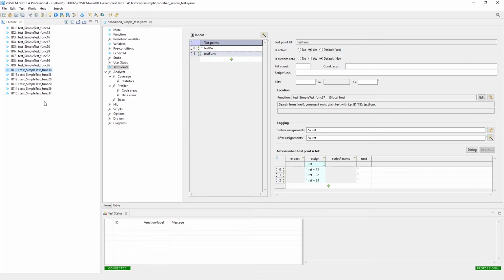So for example, in this case, I've got an Infineon Tricore TC277TF device, which is their emulation device. It's a special device that you can get from Infineon that has a little bit of extra memory for this trace feature. And that allows you to basically record some program execution or data access while the system's running. And then you can use that functionality inside the test tool as well.